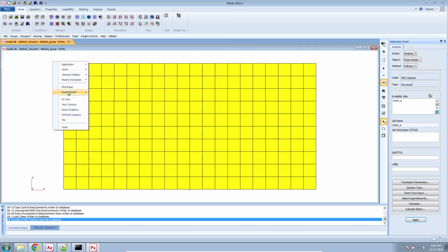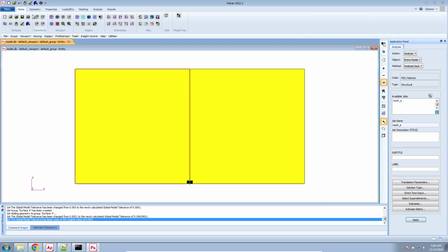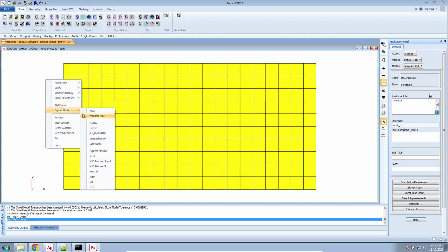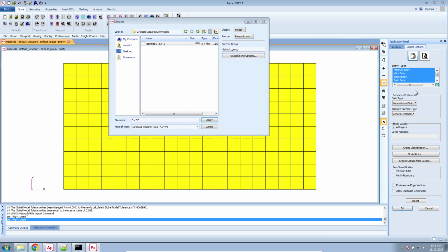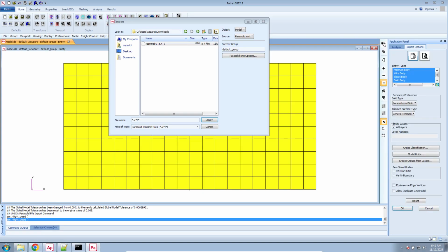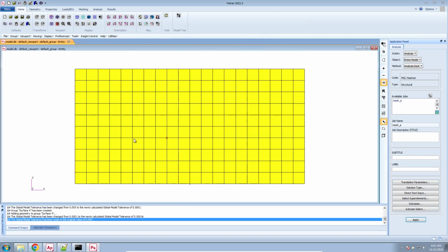So this is the mesh that we just imported. Let's go ahead and import the parasolid file. Now, one thing you have to be careful with here is the scaling factors. So let's go ahead and work on that. So import solid geometry parasolid. Here under parasolid XMT options, there's going to be an option for units. Here, let's go ahead and select none, and then we'll click OK here on the right, and then let's go ahead and do this import again.